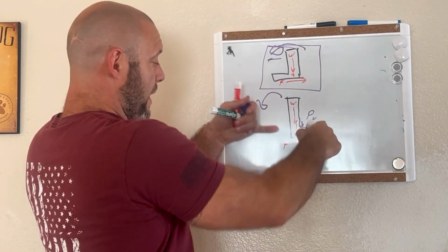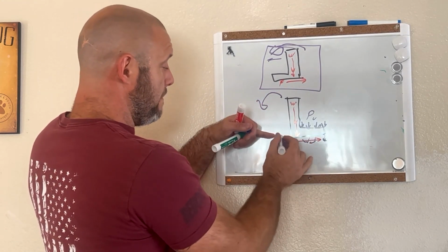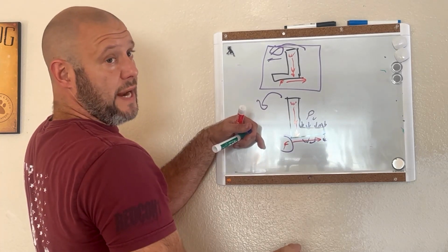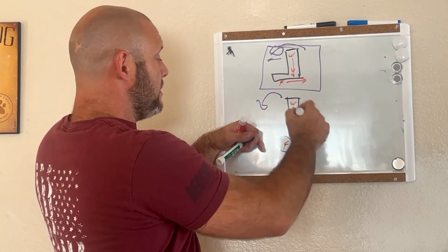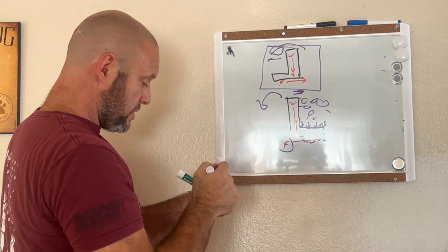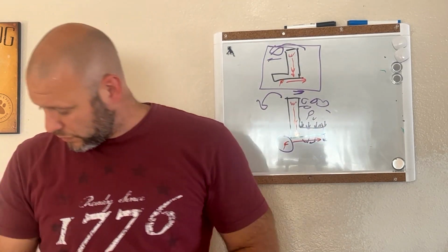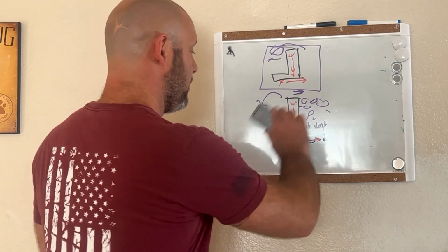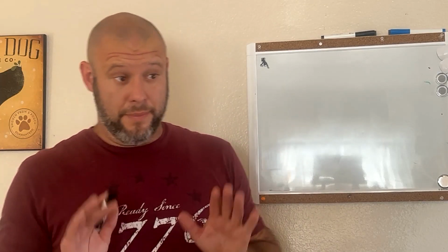This prevents this motion. This is also going to anchor down with all these passive forces resisting this overturning motion. And by putting more weight down where you have the friction, the more weight you have on that, the better the friction resistance you're going to have, especially with the geomaterial. So all of the additional weight of the soil that you're retaining up here actually helps support this entire wall, right?